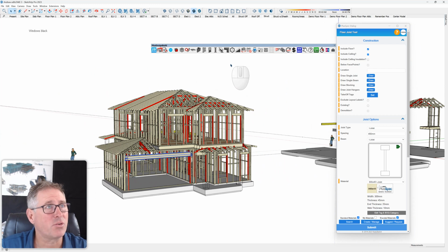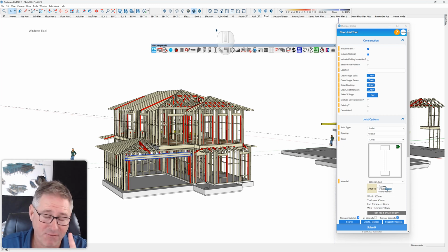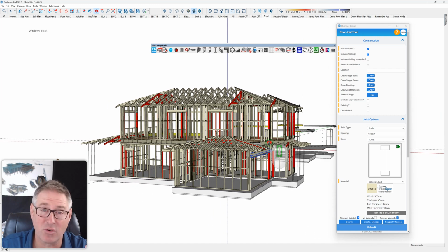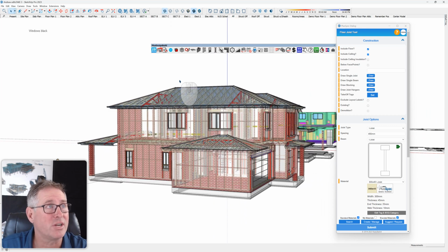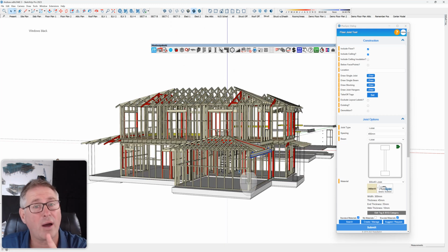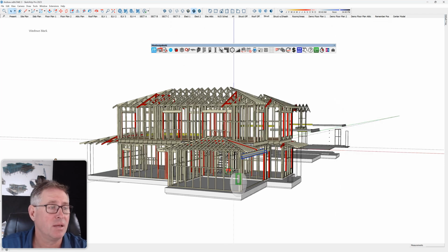There's a couple of other things with the drawing too. Now, you notice I've been using scenes to explain to you what it is that I'm talking about. And scenes, there's so much more to scenes. It's really important that you understand why scenes. The first reason is it's easier for SketchUp to deal with multiple pieces of geometry or more detailed geometry when it's not looking at everything. So to go to all and then turn it into transparent mode, your graphics card is really struggling with this. It's not a good way to do it. It's so much easier to just go, I just want to see the frame, what's going on, move forwards. But that's only one reason for creating scenes.